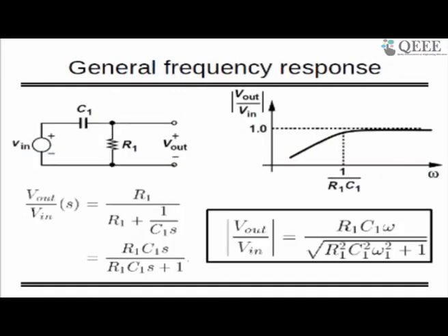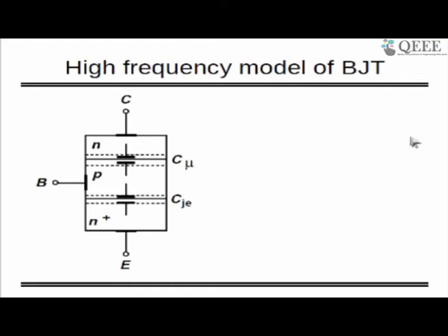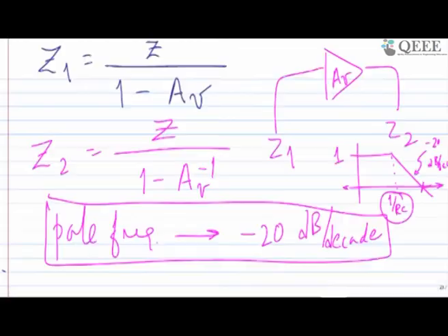Okay, so now go to the BJT, where there is a high frequency model of BJT. What I'm saying is, we agree that parasitics will be there. You don't want them, but they are there. I'm talking about capacitors, because a capacitor gets active at high frequency, or whenever there is frequency, it allows AC. It blocks DC, or it blocks a small value of AC frequency, because it depends on the capacitor value also. And it's blocked by this equation, 1 by J omega C.